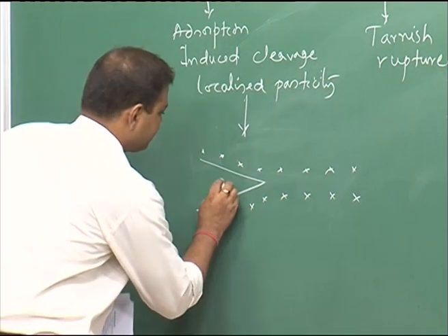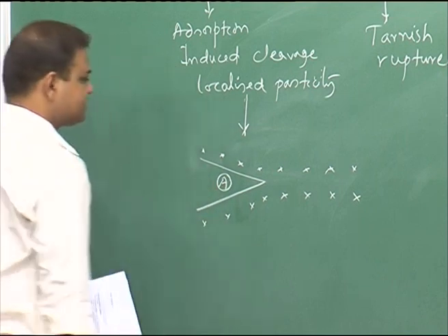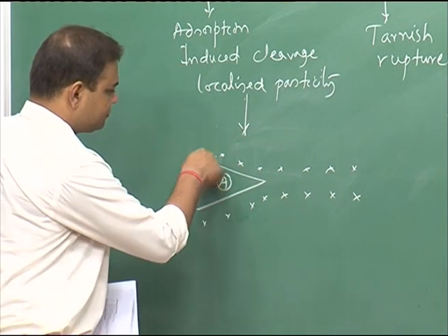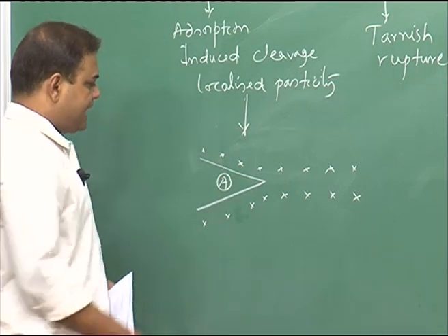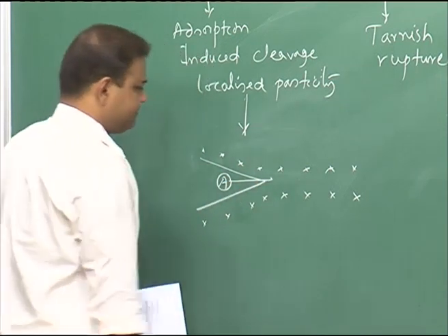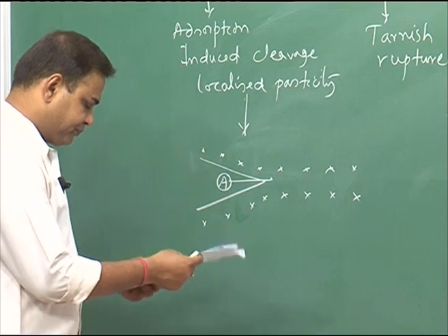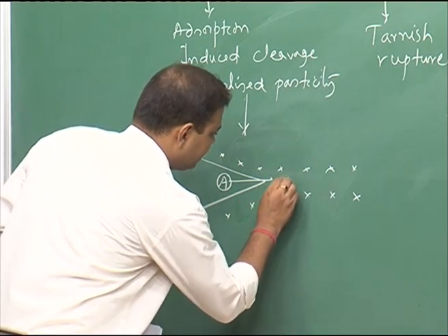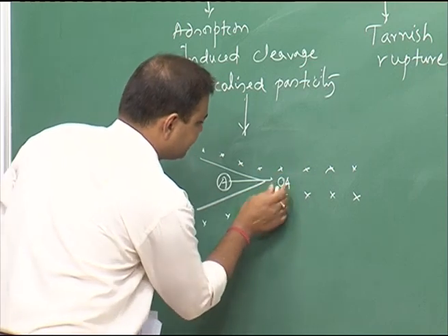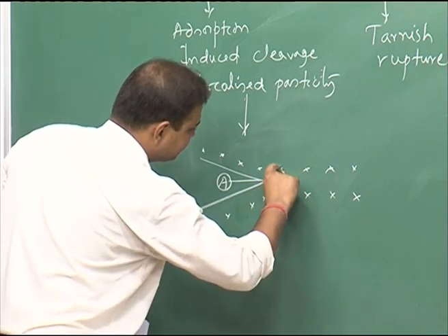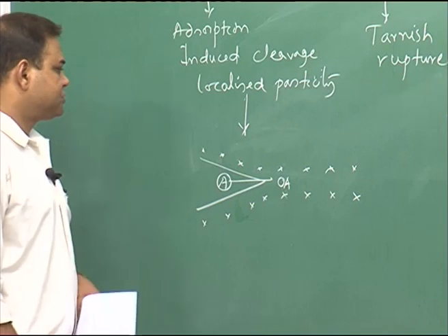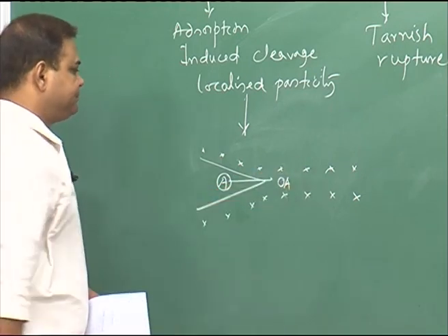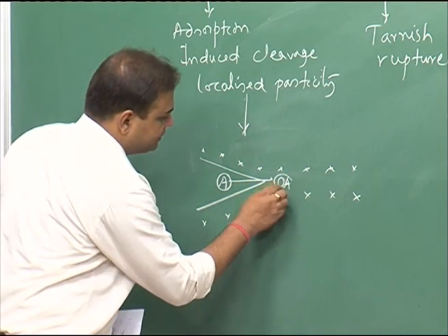This is my atomic species, which is the product of corrosion in the crack tip zone, that can enter into the lattice and is placed between two atoms of the main lattice of the metal.